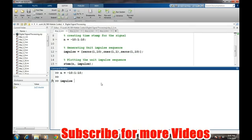From the definition of the impulse signal, it is clear that it exists only at point 0. At all other values it is 0. So from minus 10 to minus 1 it will be 0, and those zeros will be generated by the command zeros(1,10). This generates a single row vector having 10 elements, all of them 0.